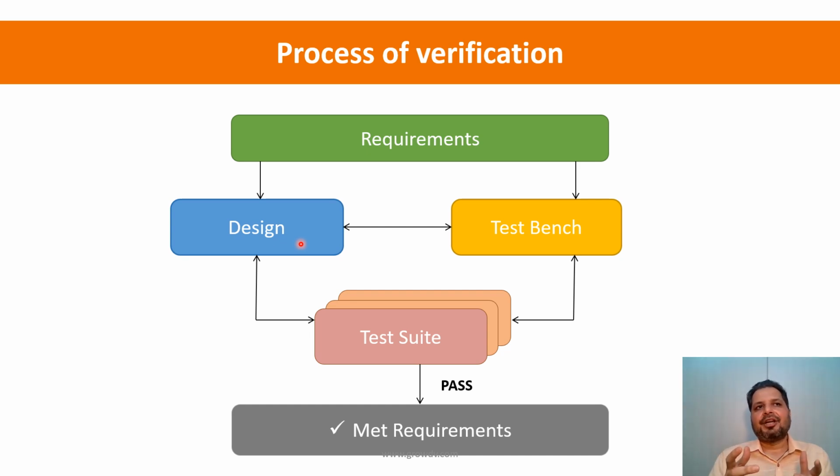We are reinterpreting a requirement in the form of, okay, we need a way in which, when we are providing a certain form of stimulus, it should not overflow, right? So that could be a very high level requirement, and the microarchitecture could have been defined as, okay, that should be implemented through a set of ready valid signals, and you assert a valid, and until the ready comes, it should not send the data, so that way there is no data loss. So a high level requirement is transformed into signal level interaction. That is the process that is happening when we are doing the design.